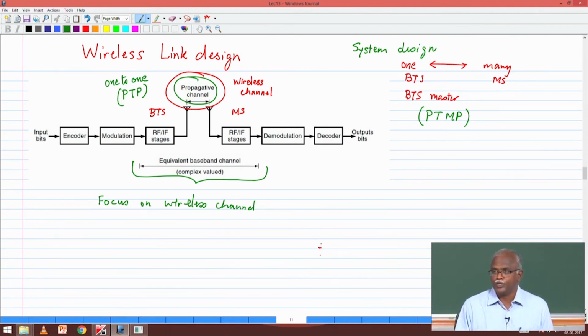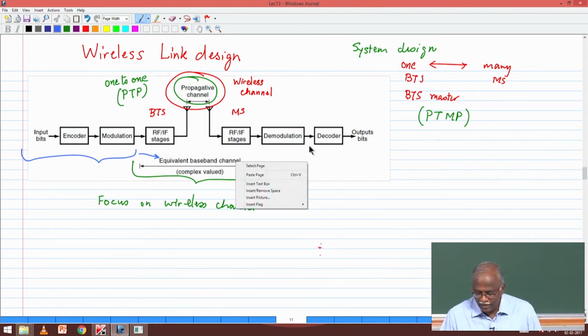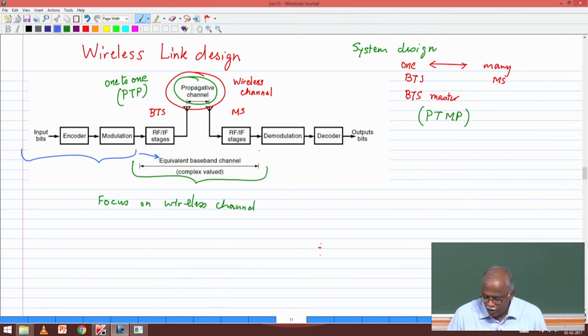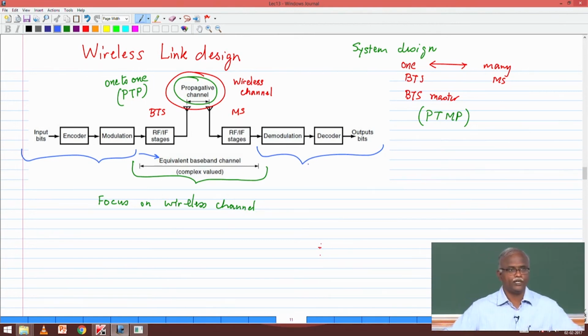What we did for the most part in digital communications was we took the transmit portion and said that I'm going to represent my signal in terms of a complex baseband signal. Then we moved over to the receive side and said, okay, I now have the complex baseband of the signal with some impairment, noise, fading, whatever it was. So you basically skipped from transmitter to receiver using complex baseband as your representation. So again, it's very different.